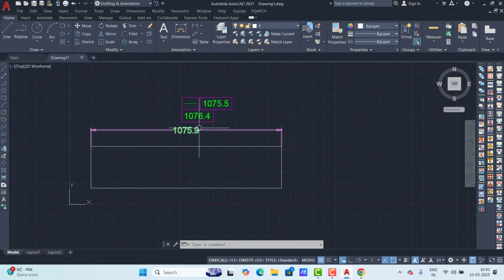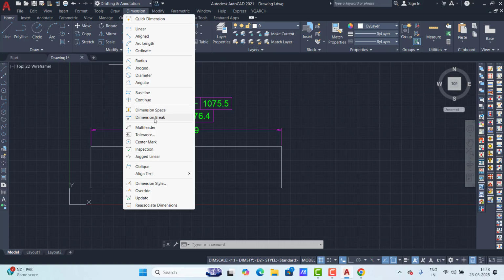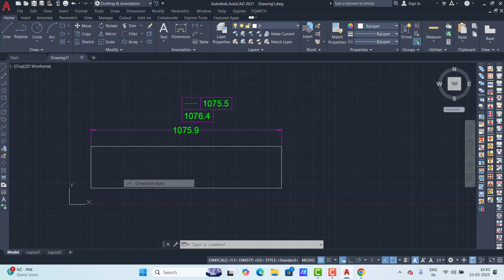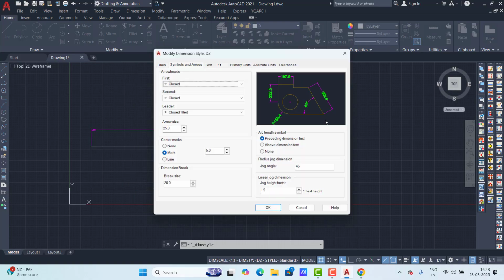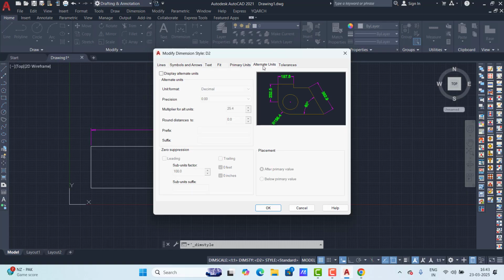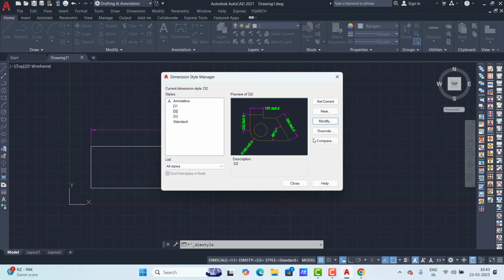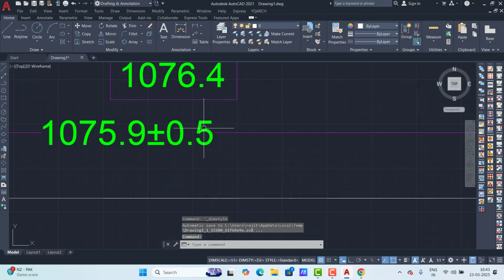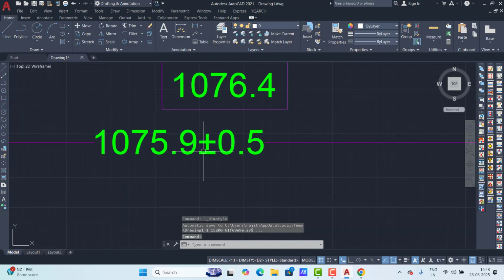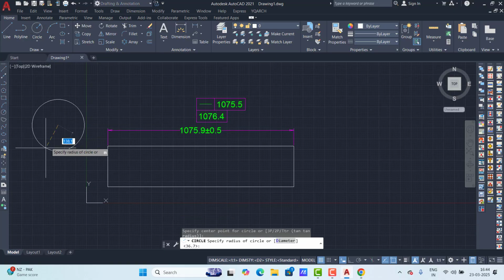So in AutoCAD this is not automatically updated, but if you learn 3D software like SolidWorks, CATIA, Creo, NX, they automatically show the actual dimension. This way the break comes, but the actual dimension comes, but here it does not. So we have to present this length, okay? In the drawing it is this one, but the dimension needs to present this one. So we select it, double click, delete, and type this value 3517.8. Okay, so manually we change it by double click.